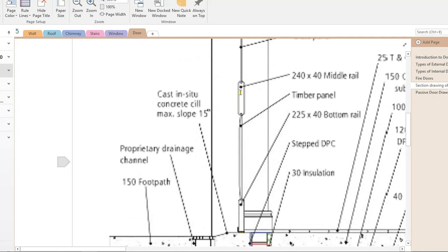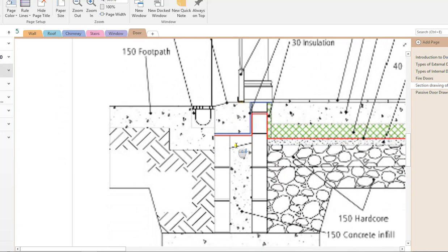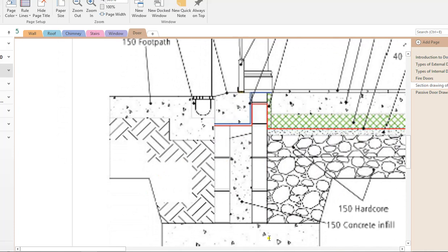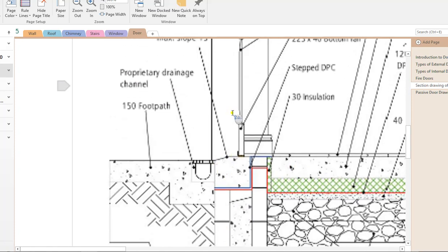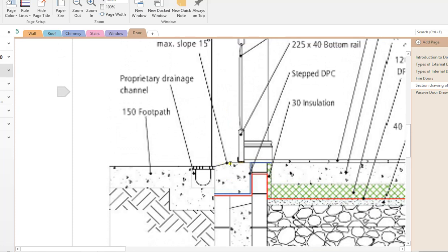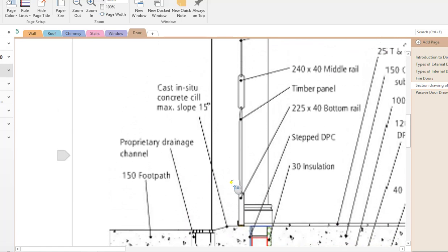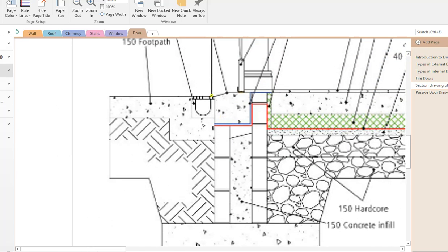We have our lock rail in the middle here, and then what we have down underneath here is the construction. Now a lot of this construction has now changed. There's no longer any cavity fill placed in here. The radon barrier is still placed in. We still have insulation on the floor here. This concrete sill here has to be put in, but we'll have a look at how we draw this. And then we have this water drain channel here, that's still placed in. Now what's labelled here is a 15 degree pitch on this piece of concrete, but we'll have a look at that in further detail.